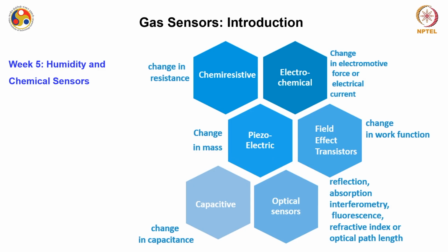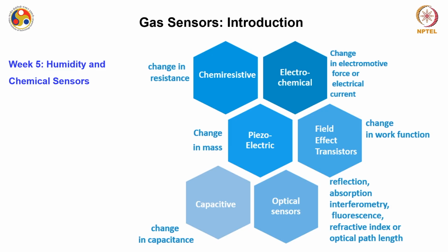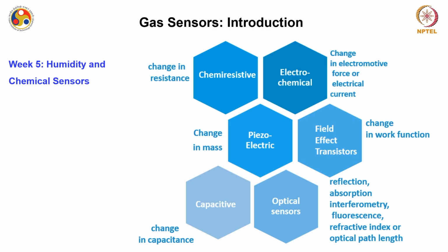Okay. In the chemical sensor, we have also seen that there are different transduction techniques to detect these chemicals, including chemiresistive devices, where a simple change in resistance is measured with respect to the molecules which we want to detect. So you have a surface of a receptor, you have a transducer, and these molecules interact with the receptor, and accordingly the receptor changes its resistance. Okay. Then we have capacitive devices, where this change is not in terms of resistance but in terms of capacitance.